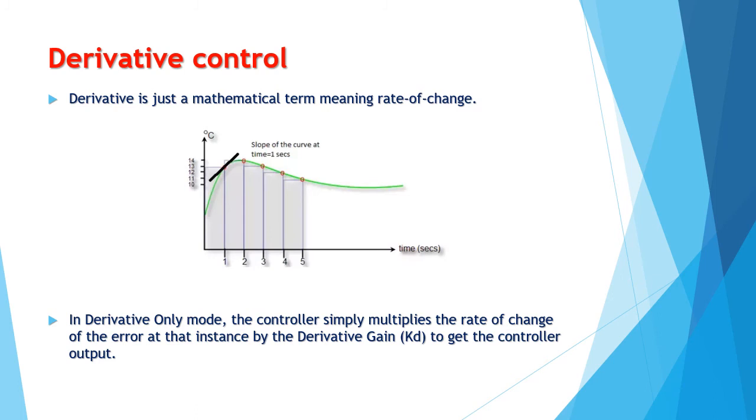The tricky thing about PID controllers is that you need to tune Kp, Ki, and Kd to suitable values to have a good controller. The other thing is to use the correct components of P, I, and D according to your application or system.